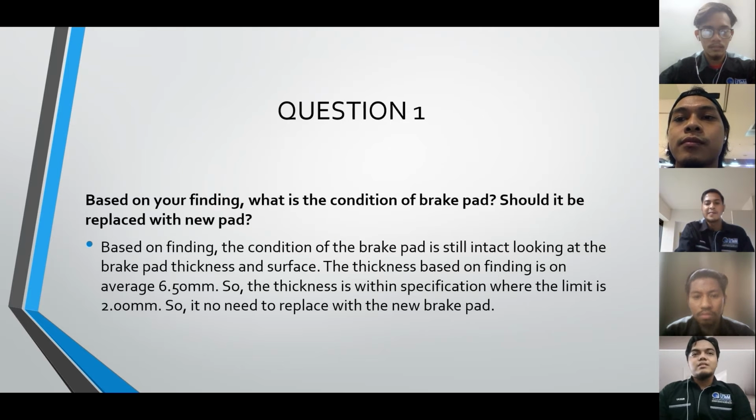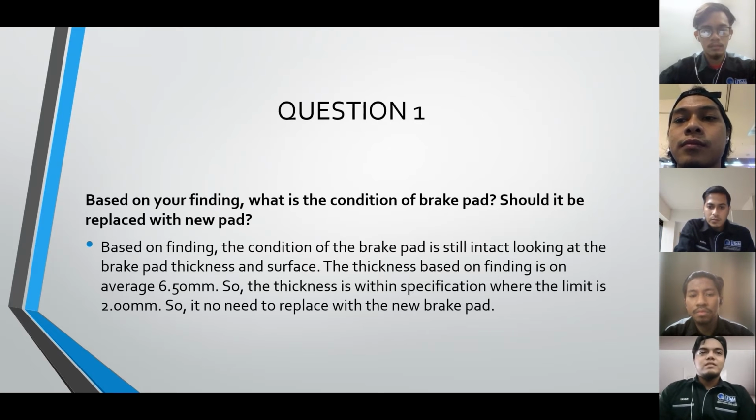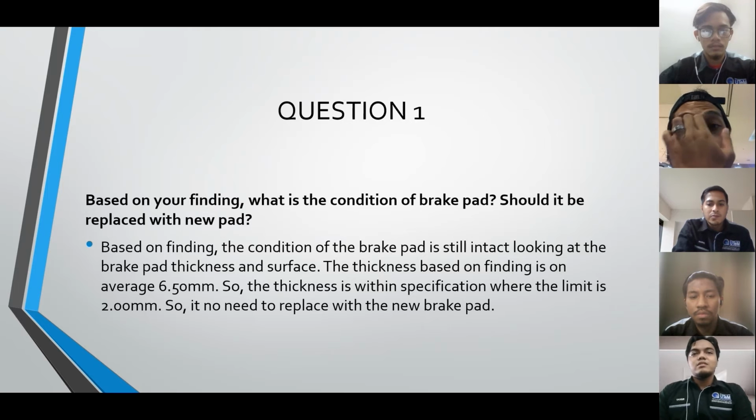Looking at the brake pad thickness and surface, the thickness based on our finding is on average 6.5 millimeters. So the thickness is within the specification, where the limit of the brake pad is 2.0 mm. So there is no need to replace it with a new brake pad.